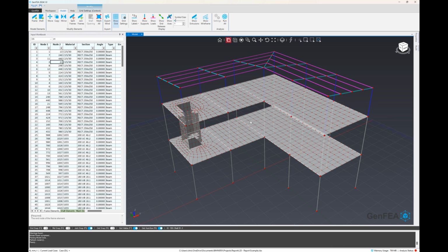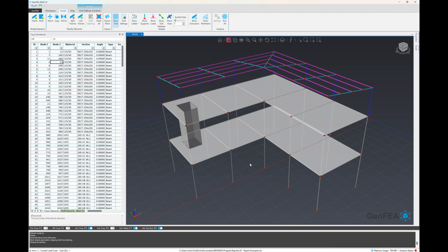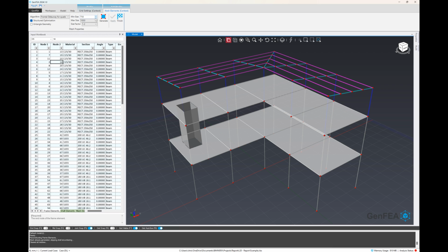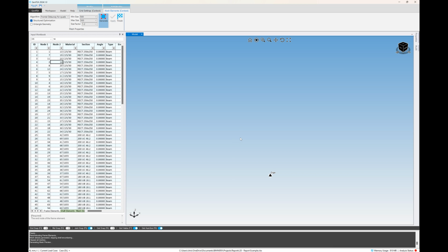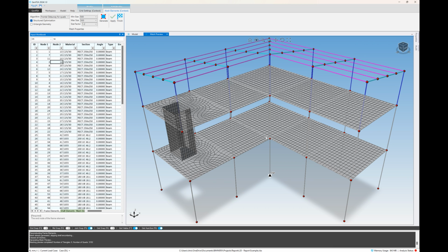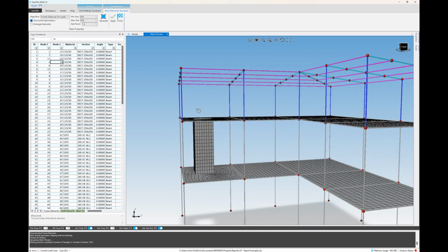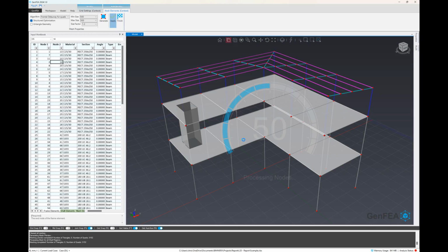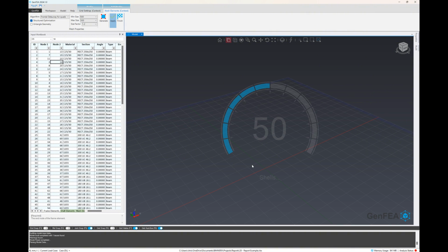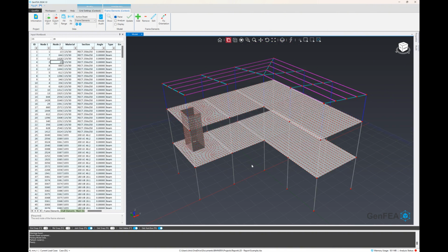At any point, if you wanted to change the mesh, you can simply head over and click on the mesh tool button. If you have existing mesh in the model, it's going to warn that the mesh will be cleared. We can say yes, and we can go ahead and generate the mesh again. So if we want 500 by 500 minimum and maximum mesh, we can hit apply, choose the structured optimization, and see the results. And then, of course, just like before, we bring the mesh in, the discretization happens automatically, and we have the result. And there you have it.